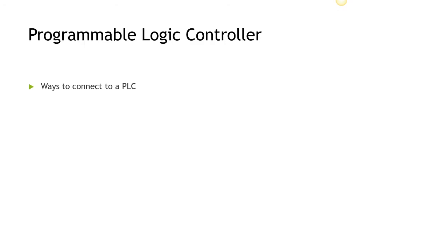There's a couple of different ways that we can connect to our PLC, and this pretty much follows every PLC. You can either connect to it serially or you can connect to it over Ethernet. There's also DeviceNet that we'll hopefully get into this semester, but we'll see if time allows for that. But these are natively the two most common nowadays. Ethernet connection has become so popular that it's kind of pushed using DeviceNet or Modbus out of the way.